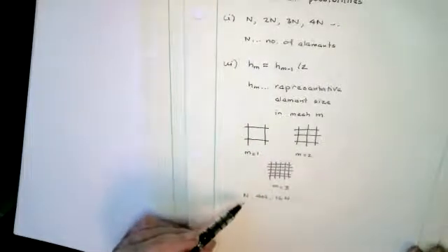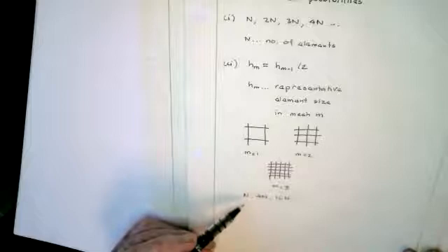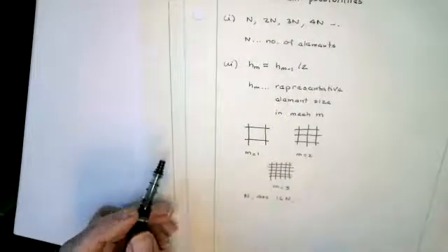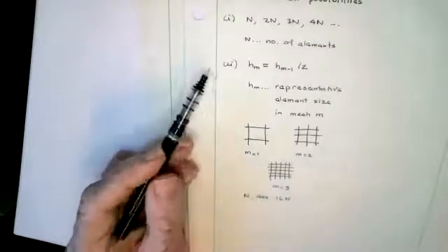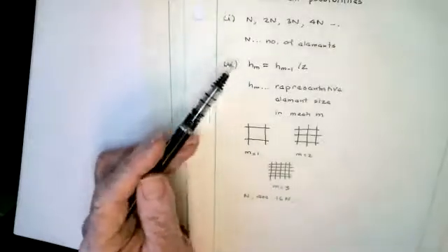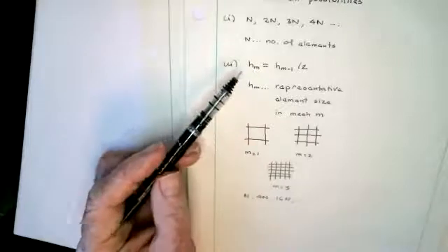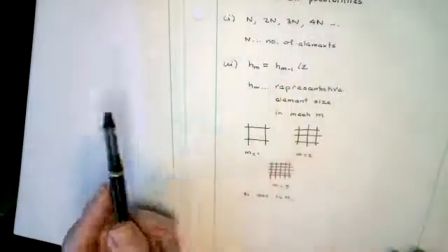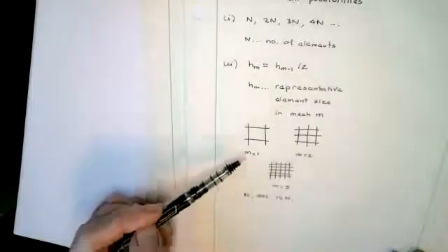Now, of course, one way of beating that would be not to start with 100,000. Then you could keep the number of elements down, and we'll come back to that. There's a little bit of a tendency by finite element users to start with a mesh they think is going to do the job, then refine it. And if they start with a mesh that has literally thousands of elements in it, then these sort of mesh sequences start to become difficult. So you really want to start with a relatively coarse mesh when you're doing this.